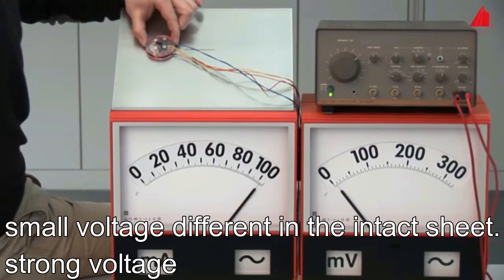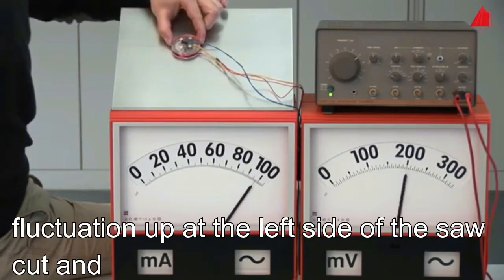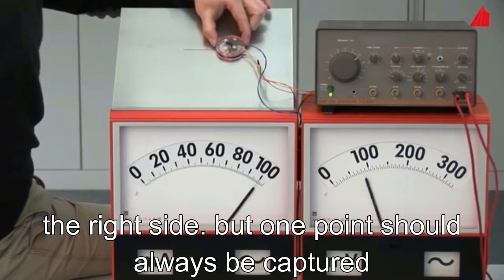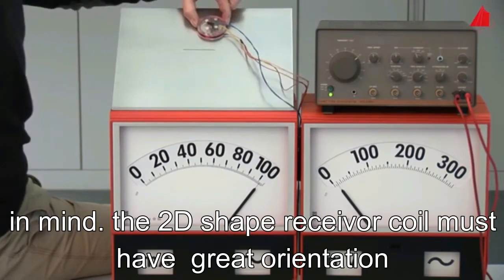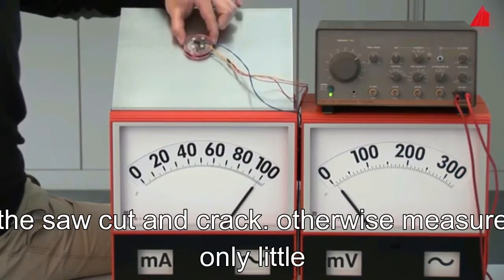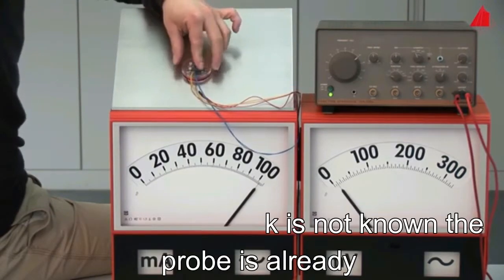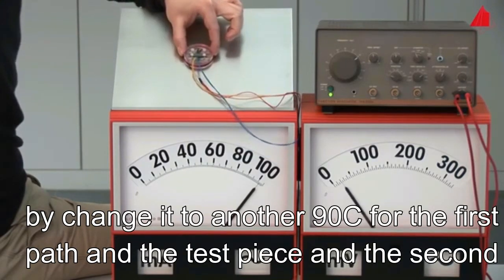Small voltage difference in the intact sheet, strong voltage fluctuations at the left side of the saw cut, and at the right side. But one point should always be kept in mind. The two D-shaped receiver coils must have the correct orientation for saw cuts and cracks. Otherwise you measure only little or nothing at all. If the orientation of cracks is not known, the probe is rotated by 90 degrees after the first pass and the test piece is scanned a second time.